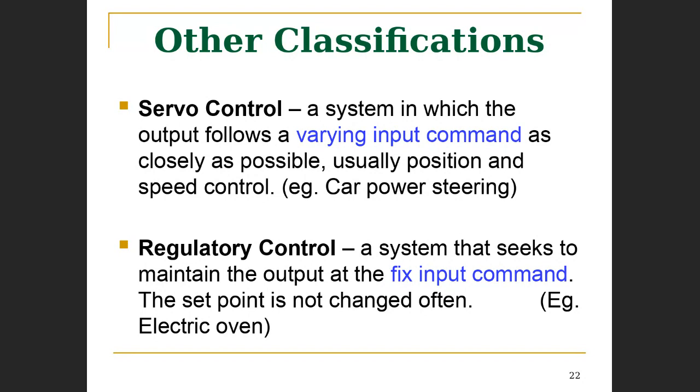What that missile does is sense the heat trail the jet leaves, and it follows it. Now, here's the point I'm making. The objective is for the missile to hit the jet, so the set point is the position of that jet. The position of that jet is constantly changing, yet the missile needs to constantly update its trajectory to achieve the desired outcome. And so we could say the control system in that missile is servo control.